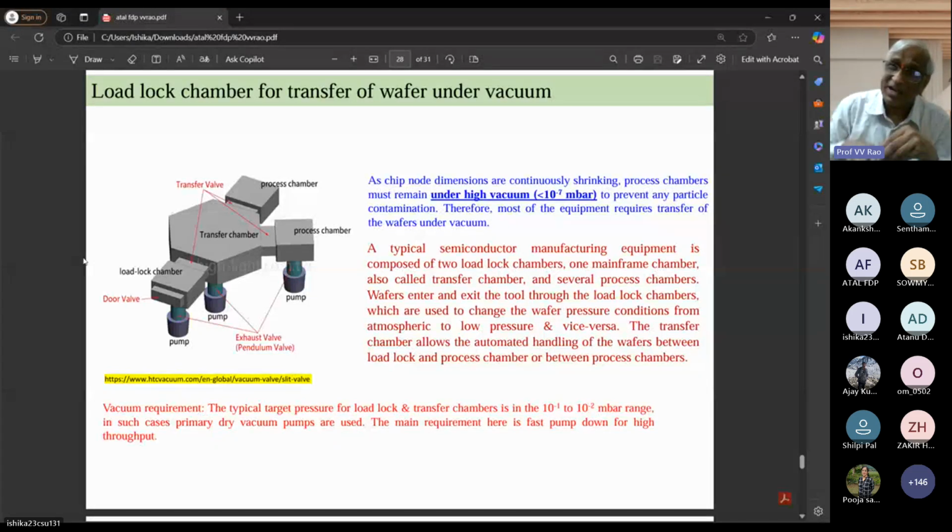If it is atmosphere, directly you cannot enter into high vacuum. So by the time this vacuum spoils, the vapor is already transferred and the valve is closed. So how much time does it take to contaminate from one vacuum chamber to the other chamber? This is also system design. It depends on the degassing.